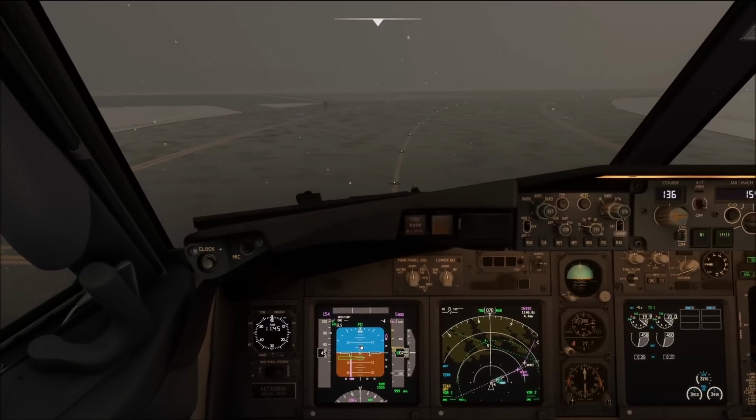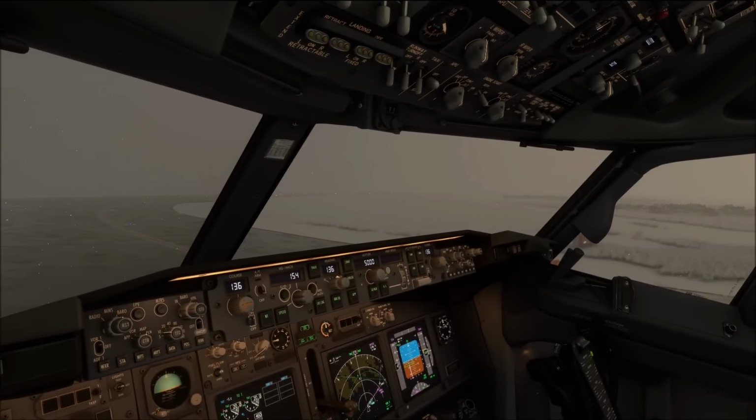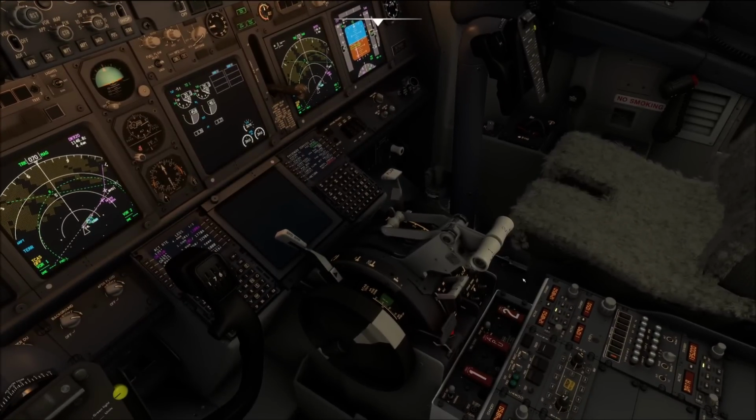We're at the holding point, our parking brake is set, now let's go ahead with our procedures. As soon as it is evident that we will not encounter any additional delay for our takeoff, we are going to start with our flap configuration check, so this is going to take a little bit of time. We will take the flaps all the way to the 40 position.